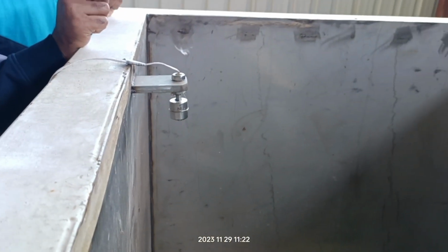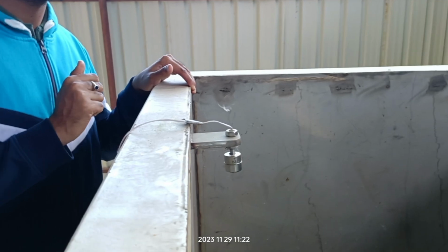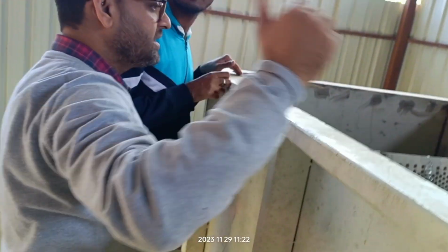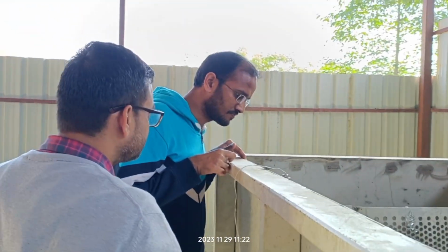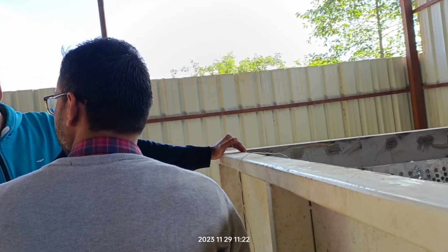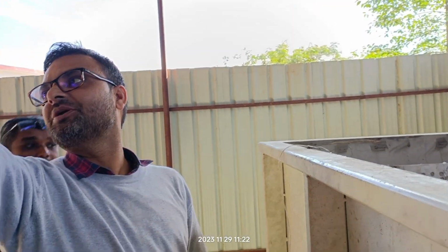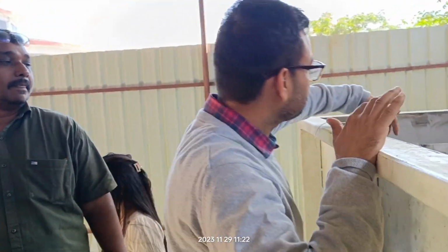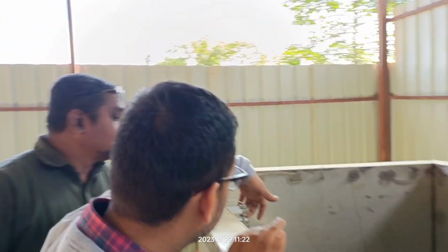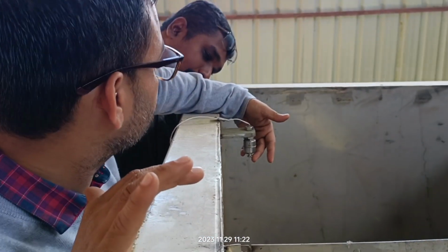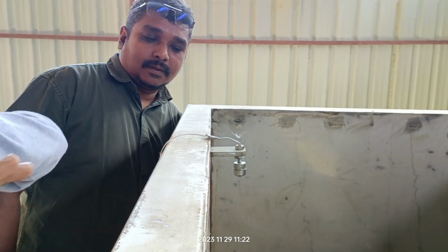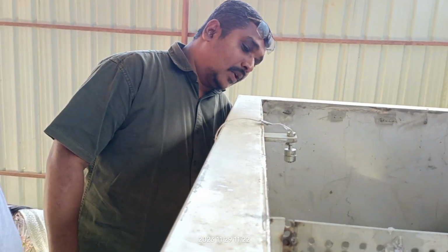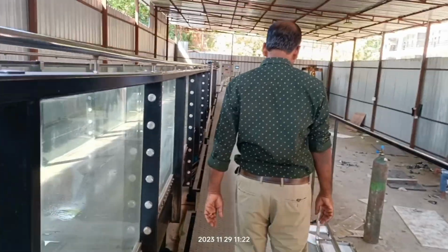If accidentally the gate is completely closed and you have switched on the pump, there will be a chance that water will spill out. And if you are here, it will be very difficult for you to run there and stop the pump. That's why the sensor is there. Okay, it will get automatically switched. If the water gets up to here, it will lift this and your pump will automatically switch off, and it will not switch on until you go there and reset that. Okay.